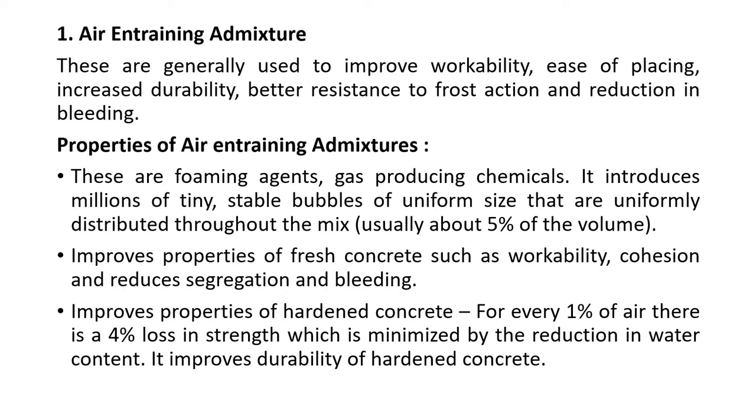They introduce millions of tiny, stable bubbles of uniform size that are uniformly distributed throughout the mix, usually about 5% of the volume. They improve properties of fresh concrete such as workability and cohesion, and reduce segregation and bleeding. For hardened concrete, for every 1% of air there is a 4% loss in strength, which is minimized by the reduction in water content. It improves durability of hardened concrete.